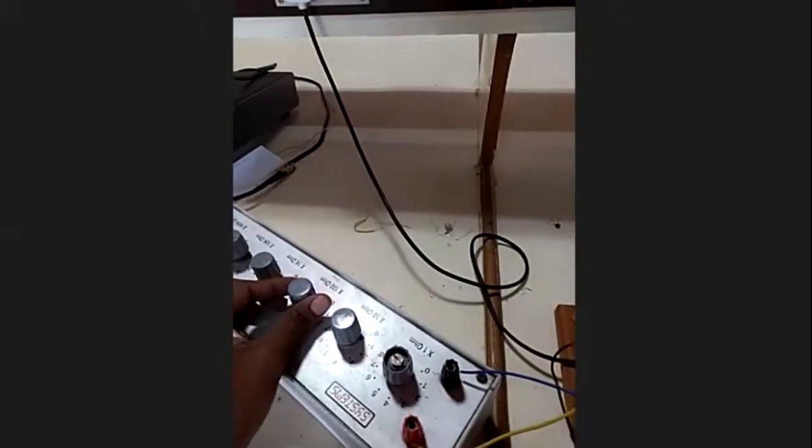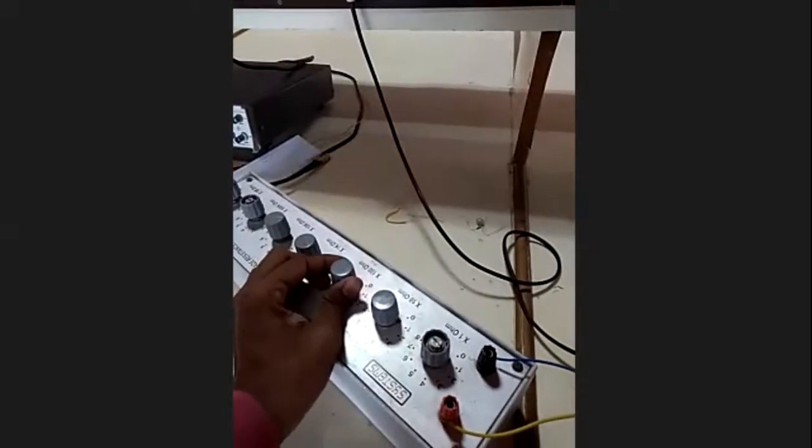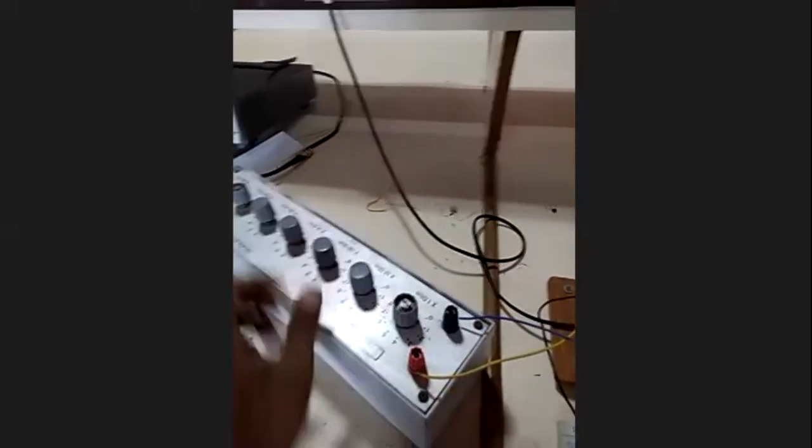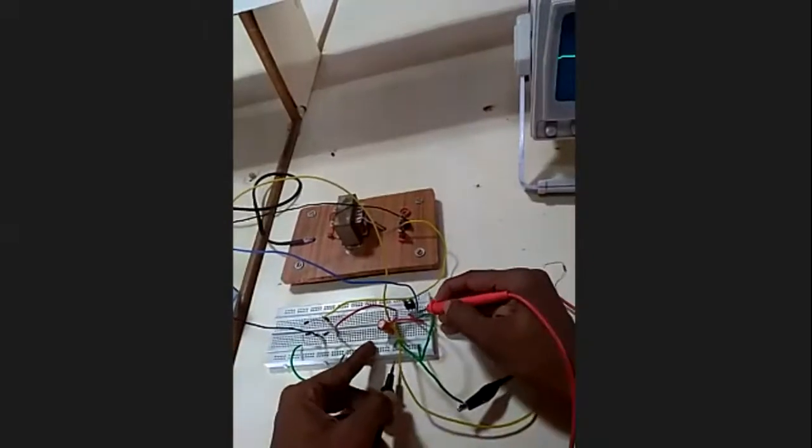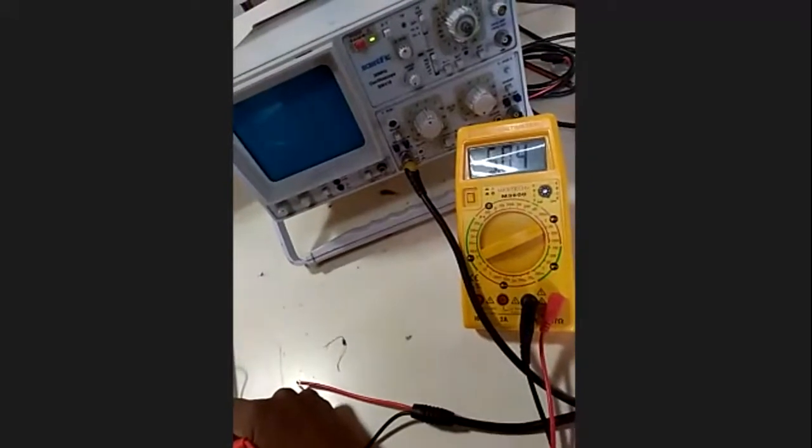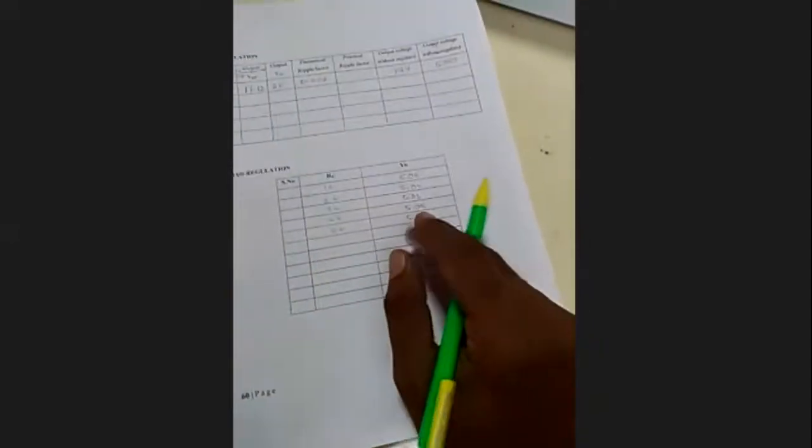So the output voltage with regulation, with load changes, is it going to be constant is what we are going to check. We are going to change the value of the resistance in the decade resistance box. I'll keep it at 2 kilo ohms and check. It is 5.04, not much variation, right? For all the values, it is around 5.04 or 5.03 or something like that. Not much variation. So we vary the value of the load resistance and still the output is regulated or constant. That is what voltage regulation means.